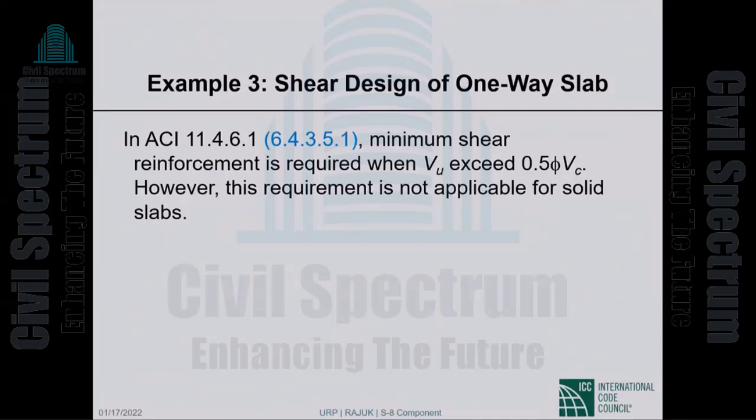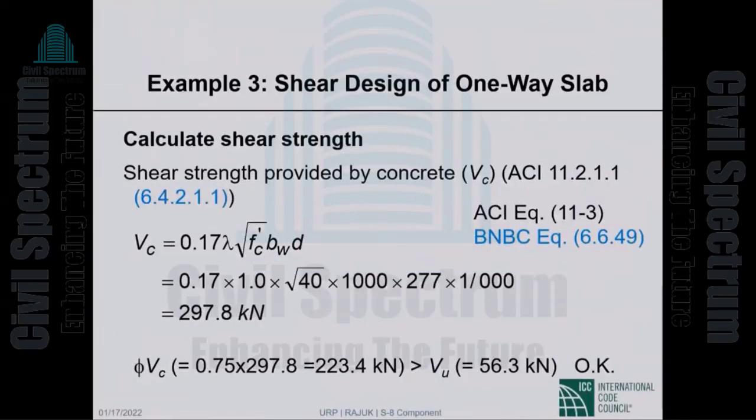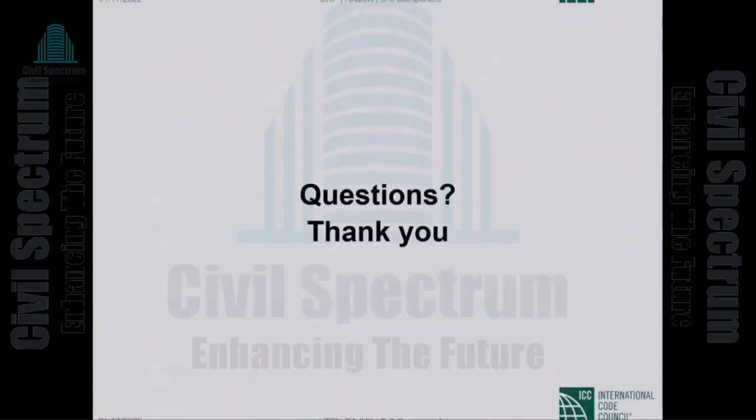Minimum shear reinforcement is required when V_u exceeds 0.5 φ V_c. However, this requirement is not applicable, remember, for solid slabs. So our design is done. We do not need any shear reinforcement.